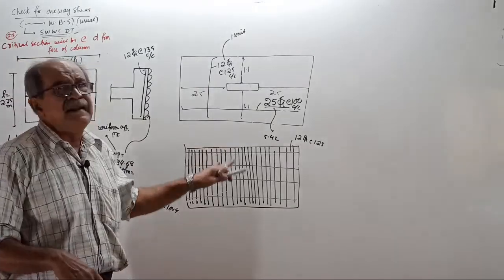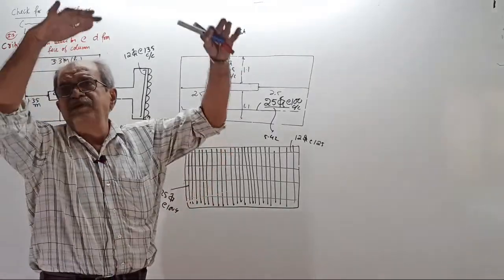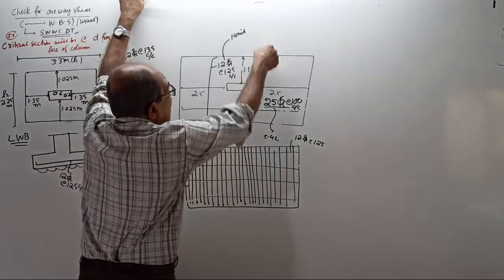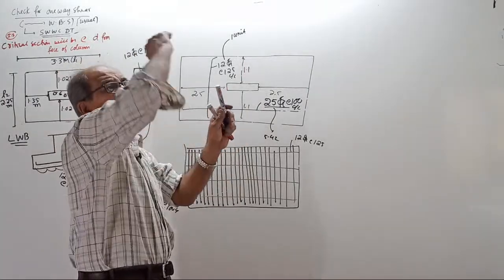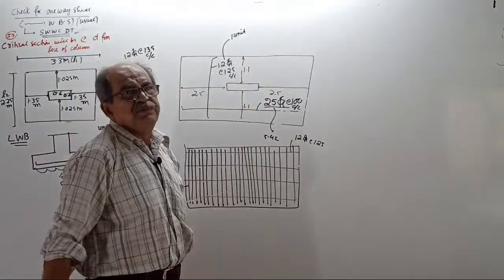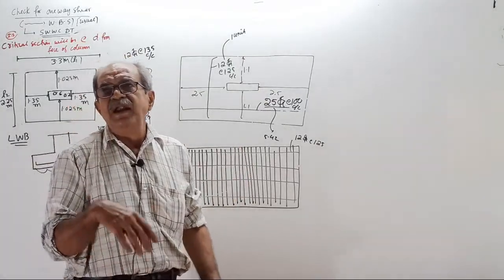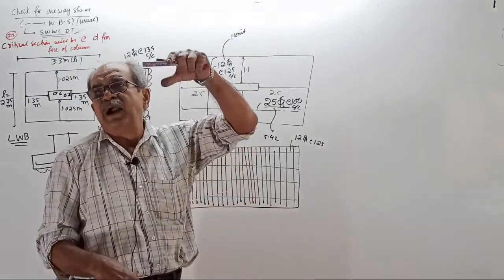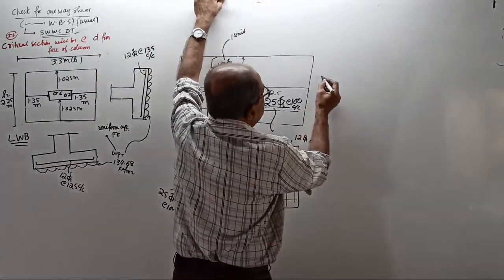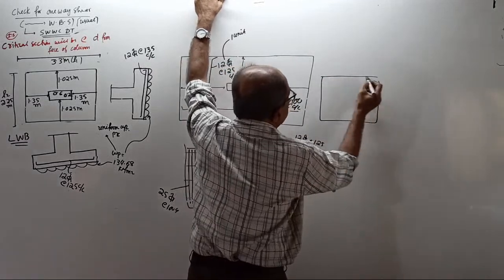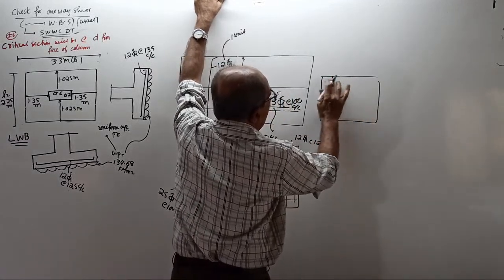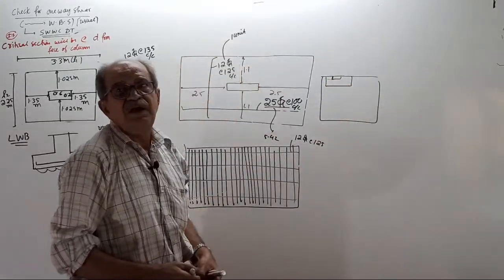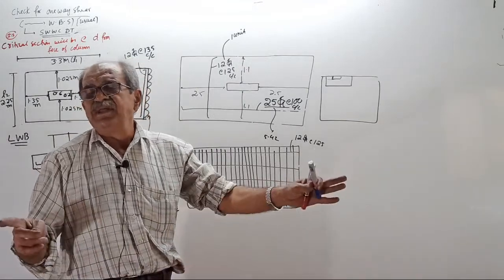Why? 100%. When the column is loaded and the centering is removed, then within no time it will get cut here. Suddenly, because of bending and shear, it will tear off. The foundation will break. But the building sometimes will still stand. Why? Sometimes in some buildings, for a column coming here, I have seen people provide footing here. Have you seen or not? Not combined, no connection with other columns.